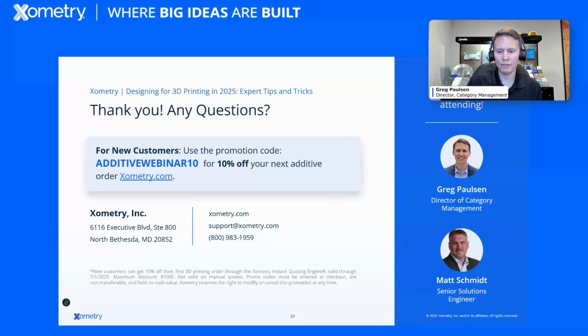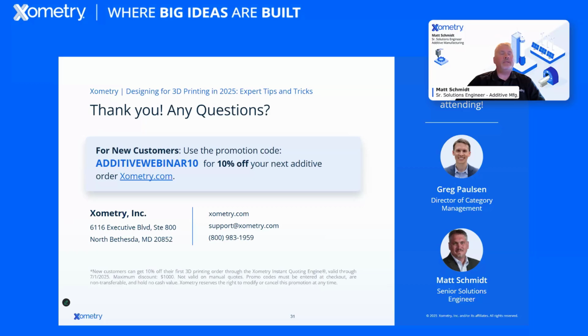So I have a question. Does shrinkage affect final parts? Do you want to touch that, Matt? Sure. So, of course, polymers shrink, especially when they're heated and cooled. The slicing software and the computational software that's provided by the OEM has an automatic scalability factor for the parts when it comes to printing, cooling, and post-processing. So you don't need to worry about that on your end.